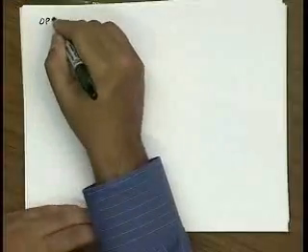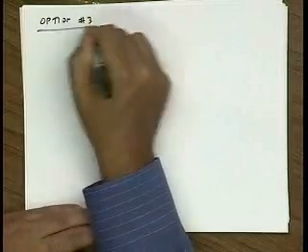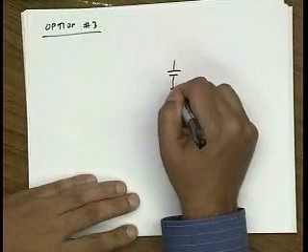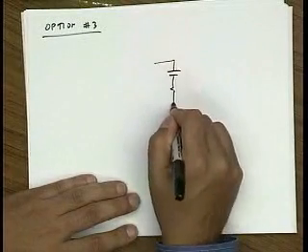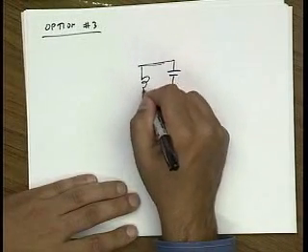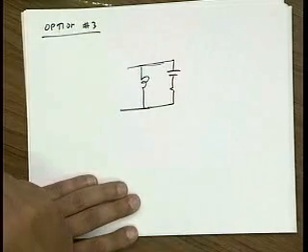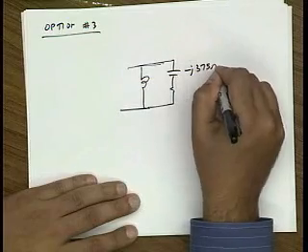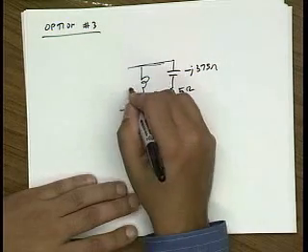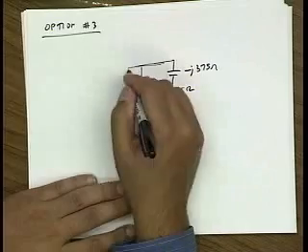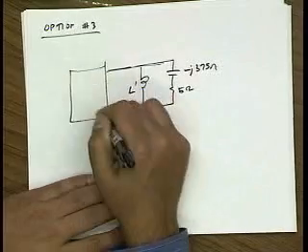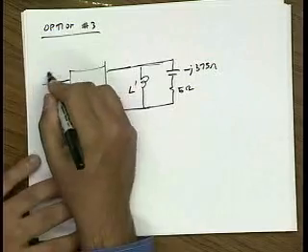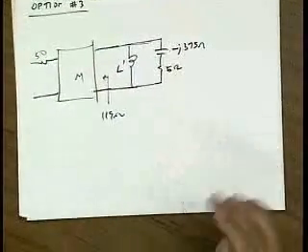Okay, well, let's not give up yet. Let's try something else. Instead of using a series resonant circuit, let's do a shunt resonant circuit. So I put an inductor in shunt with my transistor, and this is L prime, and then I use my matching network again. I still have 119 ohms here, and this is in the 50 ohm system.